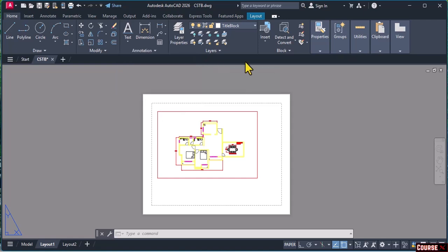Once you have done this, then come back to your drawing, and here we'll first begin by drawing a rectangle. Before we draw a rectangle, if you notice, there is a small dashed line rectangle already present on your drawing board. Now this is indicating the area in which your document would be printed. So anything which comes within this dashed line would be printed.